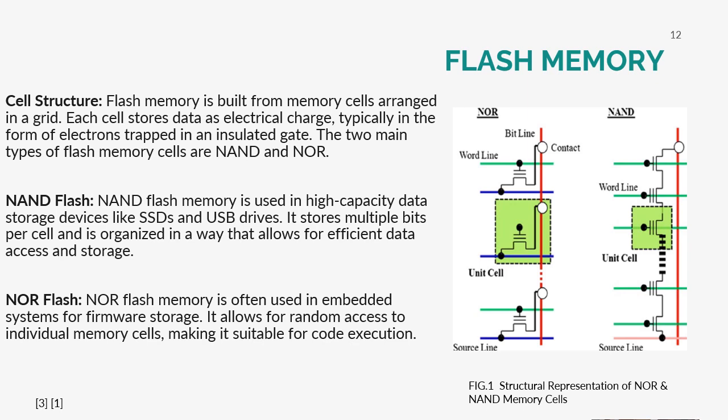The floating gate memory was used to store the information, with a tunneling current for programming and erasing operations. The charge is injected into or removed from the floating gate, and the floating gate remains in that state even after power is removed, which means that flash memory is non-volatile.